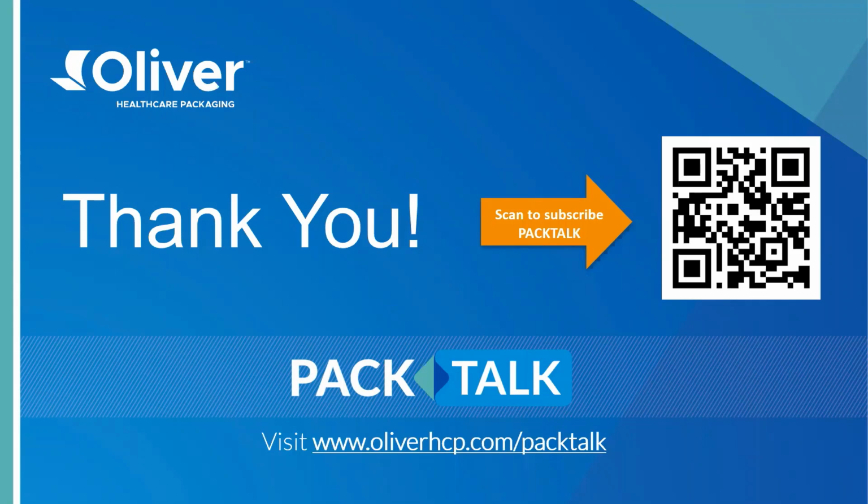If you're marrying together two films that are comprised of polyester, and polyester is going to have a higher melt point, it's not going to have as much problem with temperature. So depending on the materials you're using, you can go different directions in temperature. Same with paper. Paper's not going to melt. So the materials can drive your heat sealing parameters.